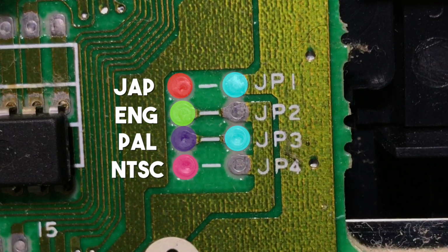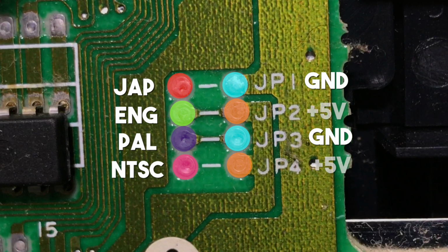The right hand pads for JP1 and JP3 are paired to a ground, while JP2 and JP3 are paired with a plus 5V signal. Depending on the revision of your Mega Drive 1 system, these JP pads might be in a completely different order, so it is very important that you pay attention to labelling of these pads.